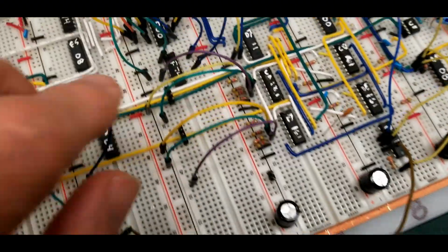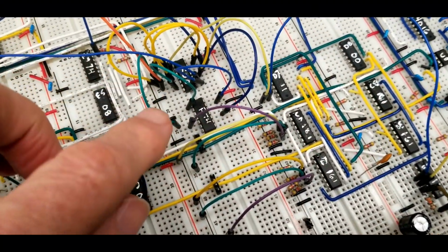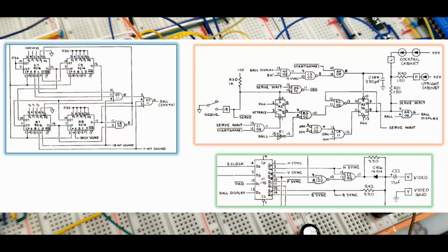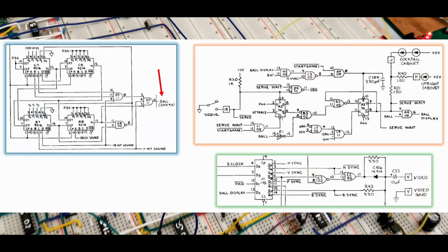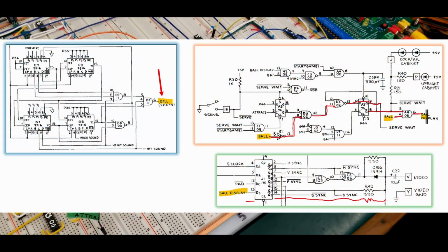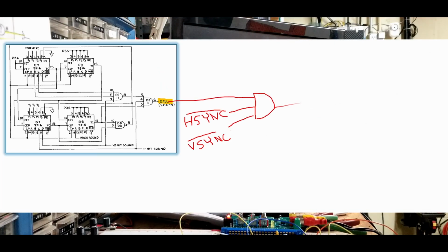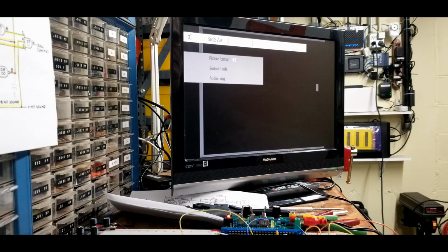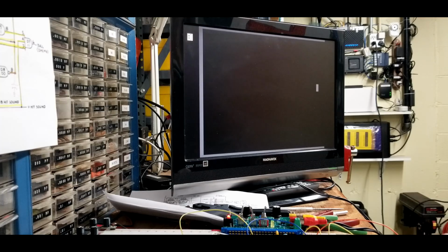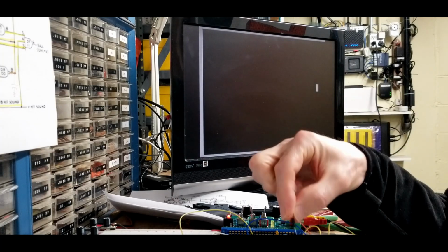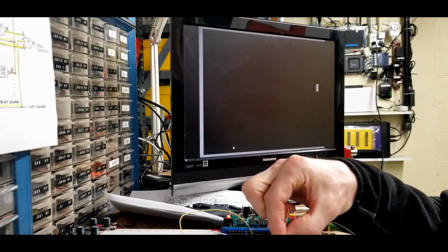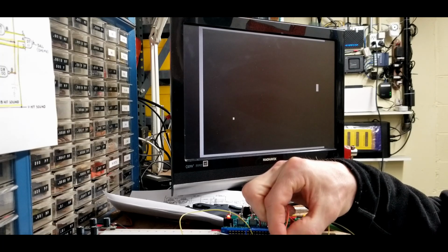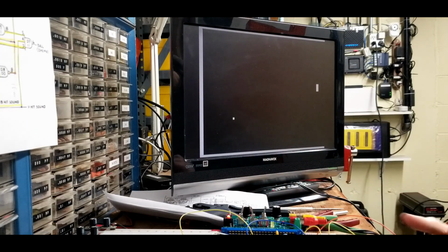Let's hardwire the load values to 4 and turn this on. This ball signal goes through a bunch of other stuff, but for now we'll just hook it up to the video bus using a spare 3-input AND gate to keep it out of the sinks. If it happens to land somewhere within the sinks after power on, we won't see it. Well, no ball. I'll poke the high order resets to get some random value. Okay, there it is. Not moving as predicted.